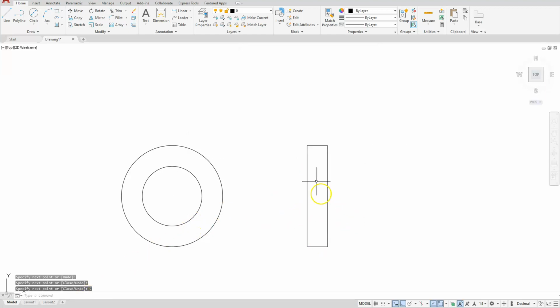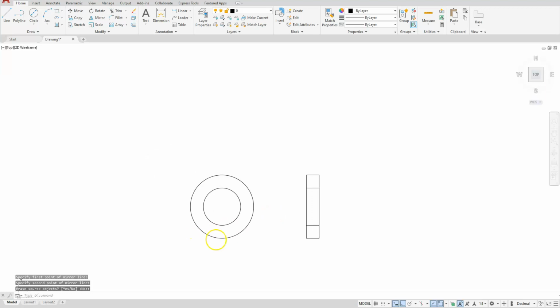The lines that are running through, the hidden lines, let's go ahead and create a line. In this case, instead of using construction lines, I'll just track from this quadrant to that intersection to where it's perpendicular. Let's go ahead and use the mirror command to create the top one. Let's go from this midpoint to this midpoint. Okay, so our drawing portion of this is done.